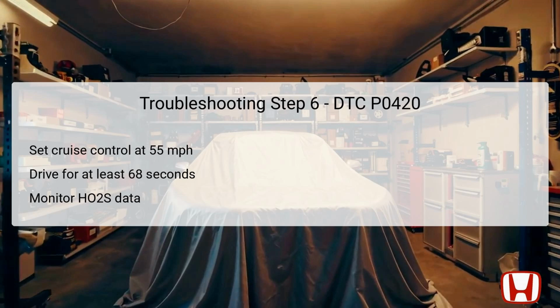It's paramount to ensure that other environmental conditions are favorable, providing the most accurate data possible. If the system is reset by disconnecting the battery, extending the duration to 4 minutes is advised to gather ample data. Ultimately, this controlled environment aims to capture the last diagnostic details essential for determining if further repairs are necessary.